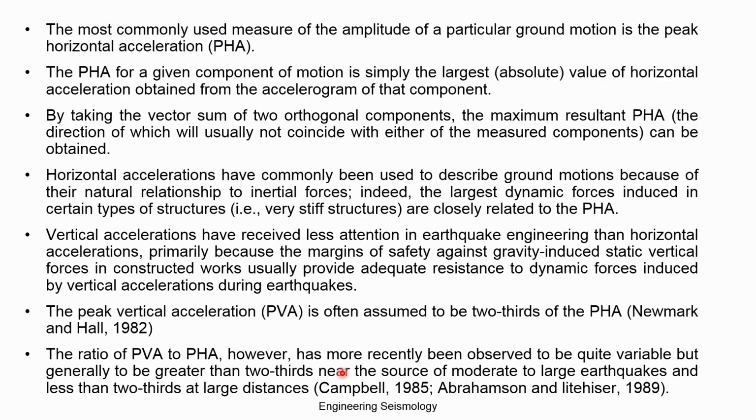So this peak acceleration is also called the peak horizontal acceleration, because as we have seen, each earthquake has 3 components, 2 horizontal and 1 vertical. So the peak ground motion means the maximum of that. When this knowledge was developed, there was a record from the rock as well as a record from the ground surface, so how do you differentiate that? That's why they call it the peak horizontal acceleration. It may be recorded at rock or at ground, it does not matter. You can also call it peak ground motion, or peak horizontal motion, or peak horizontal acceleration, the PHA.